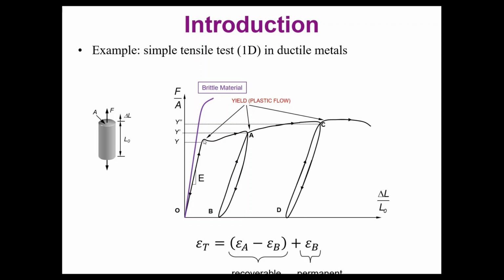But once we reach this value and we change the behavior, because this value is the slope, so the tangent of this line, the value for the Young modulus, if you want to call it Young modulus, is not the Young modulus anymore. The value of this parameter is not constant anymore and will change along this curve that is describing the deformations or the strains in relation with the stresses when you are doing a test on this bar.